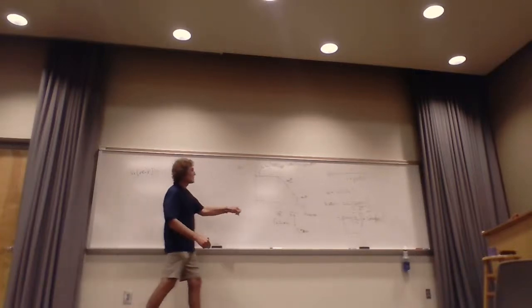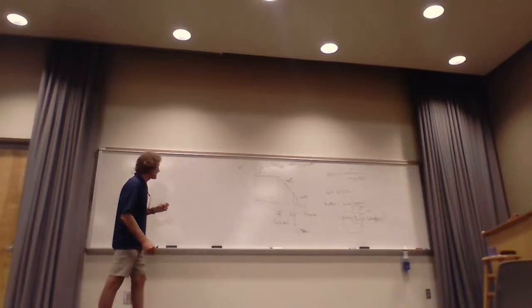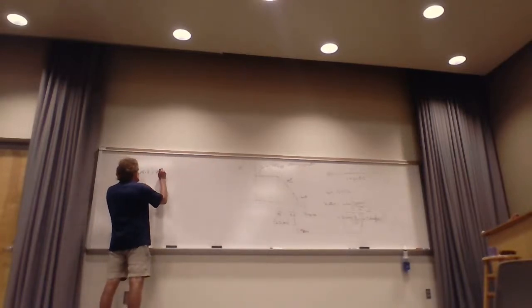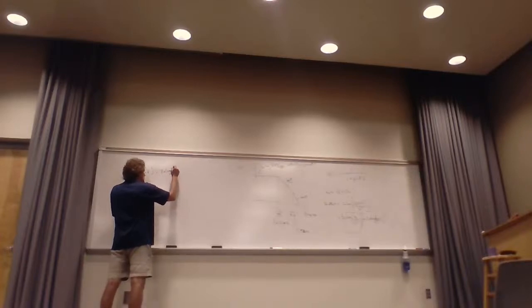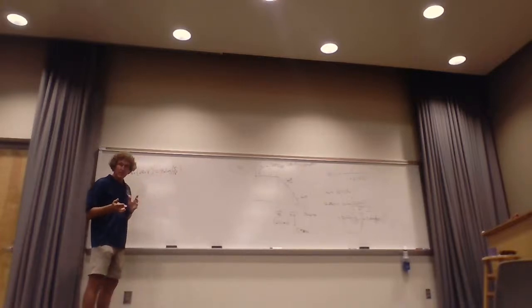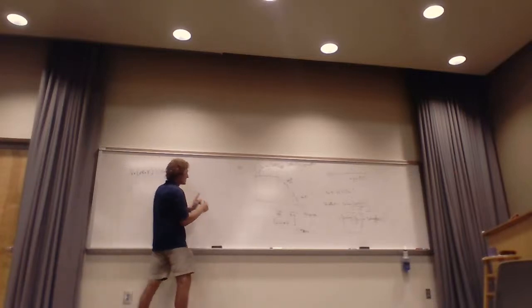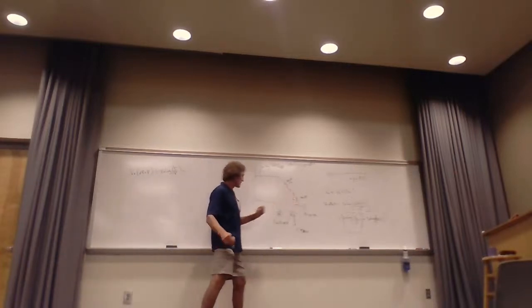By the way, for this one, since tau over T is 50%, or 1/2 times 2, it just means it's 20 times log of A over 10 to the minus 6. So the first part is 20 times the log of 5 over 10 to the minus 6, and that's 134 dB microvolts. Then, now we're over this range right here.